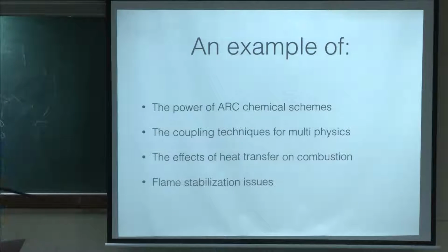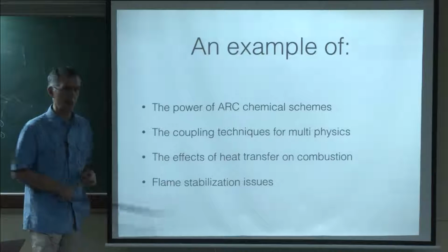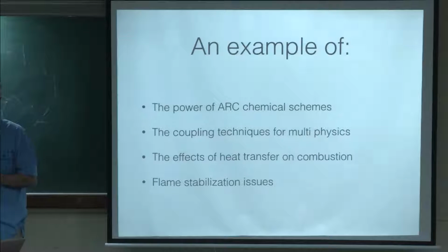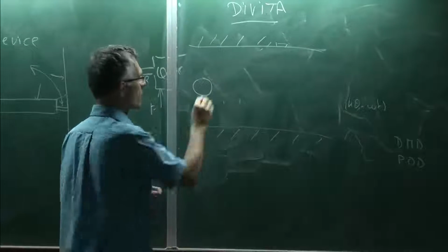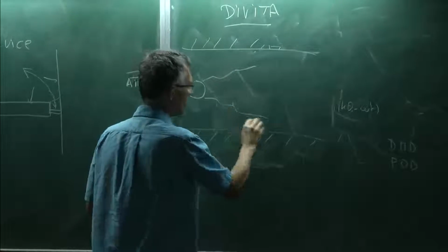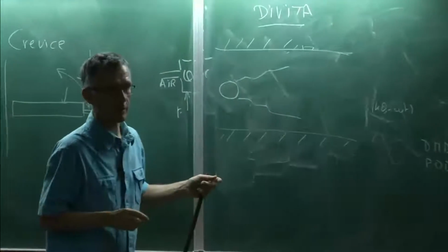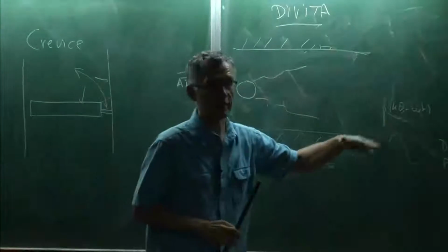I haven't talked much about flame stabilization. I would say that flame stabilization is not the same thing as flame stability. Okay? Flame stabilization really means that if you design a burner so that the flame stabilizes here, either it will or it will not. If the flame is quenched, it's not stabilized here.